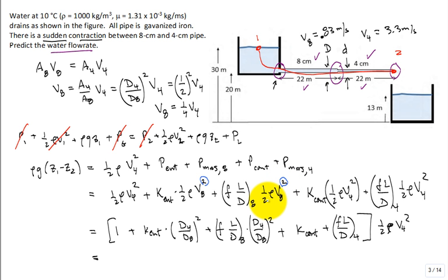When you replace V8 in that by V4 times the ratio of diameter squared, this becomes, let's fix it right now, 4. That makes sense? So this ratio here is not a fourth, but guess what that ratio is? Large diameter pipes make it easy for fluid to go through at relatively high speeds. And so that really knocks it down. So this is a 16th right there. All right?